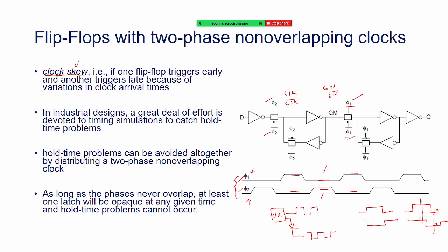In RTL design or physical design, when you use a compiler, when you do the synthesis of this circuit, synthesis is the process of connecting the inputs, outputs, and defining the clock. Once you define it in the code, the tool will automatically use the logic gates, flip-flops, everything, and connect them together according to your function. So if this situation of clock skew occurs, the flip-flops and these pass gates will not trigger exactly at the same time. There will be some mismatch. One will trigger earlier than the other. So obviously the circuit will not work as expected.